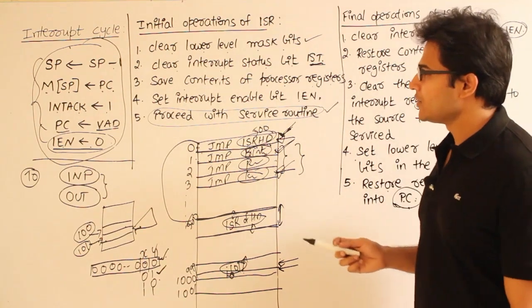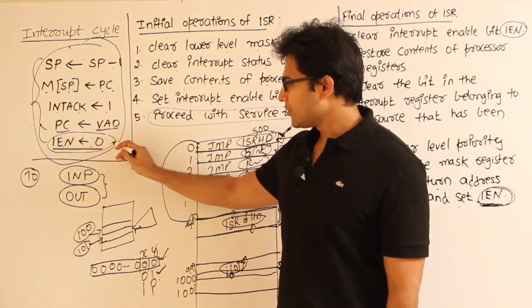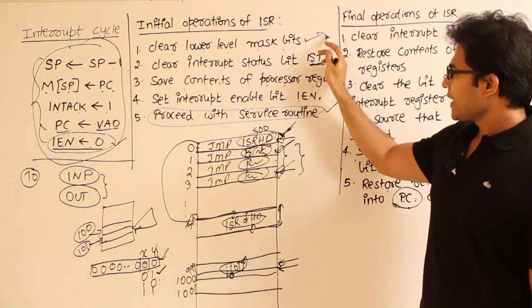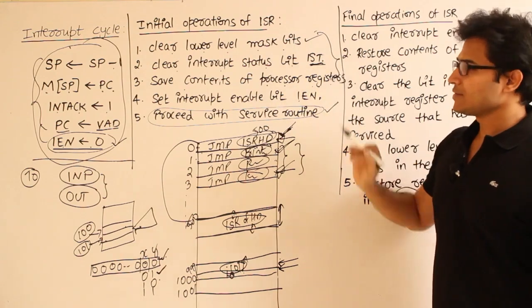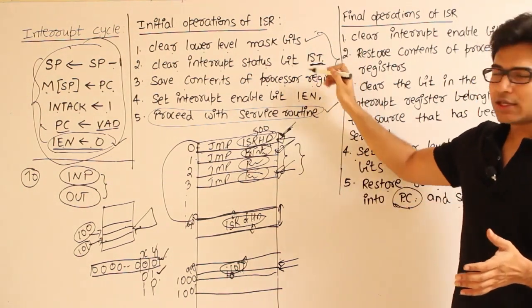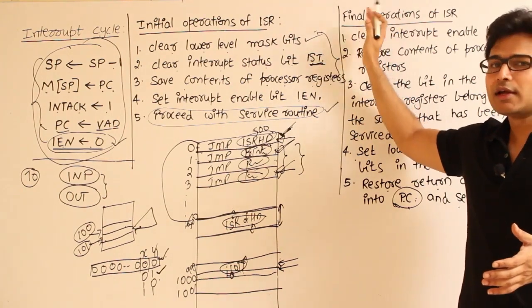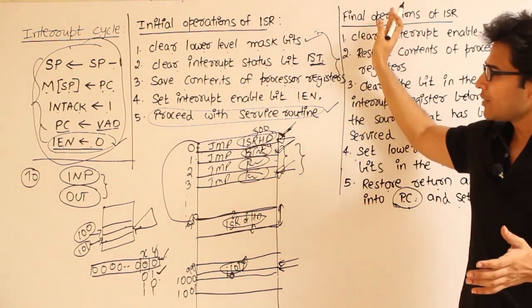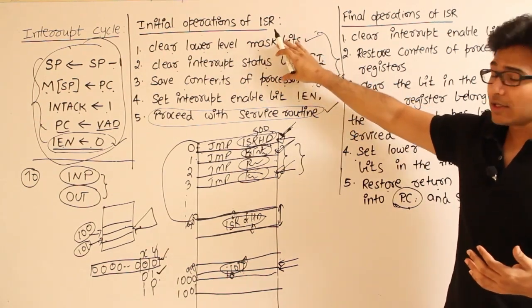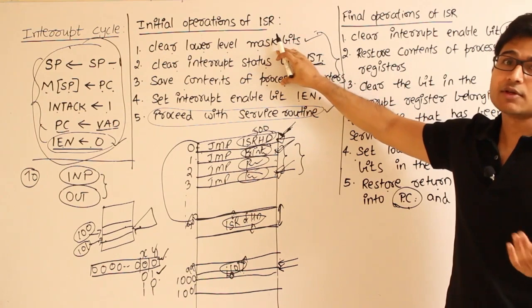done. If you observe, at the end of the interrupt cycle, we have disabled the interrupts and again we are doing certain actions, and during these actions we don't want to be interrupted, because if you get interrupted in between and go to some other interrupt handling, this will lead to ambiguity, which means there's a chance that this particular request will be lost.